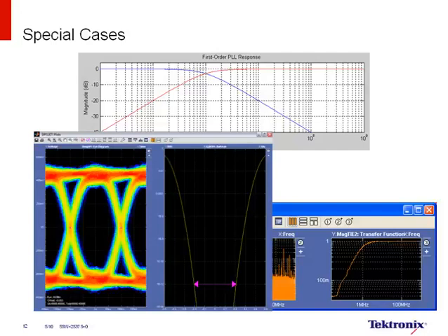The reason is because the BER closure is extrapolated out, so for example 10 to the 12, and the eye diagram is measured only up to 10 to the 5. If you were to go and look at the BER at 10 to the 5, you will see that it is directly correlated to the eye diagram closure.